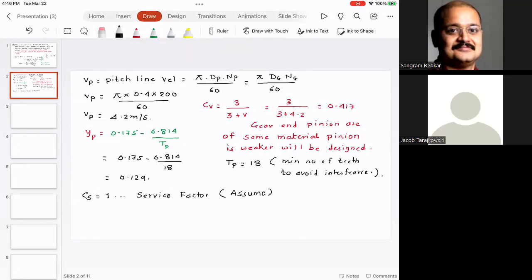For example, service factor of 1 usually means that in 24 hours, the machine is running for 8 to 10 hours. If it is more than 8 to 10 hours, it's utilized more than the regular service hours, so it's heavy use, not normal use. Service factor 1 is for normal use. You can go up to 1.2 if it is used continuously. If it is heavily loaded in a harsh environment, you can go all the way up to 1.3 to 1.35.